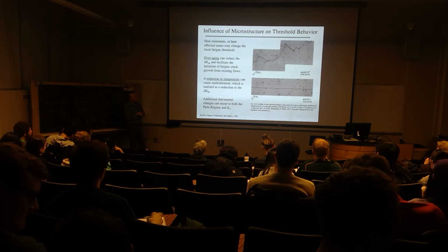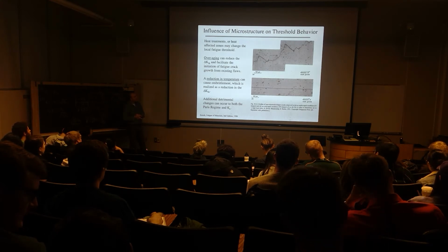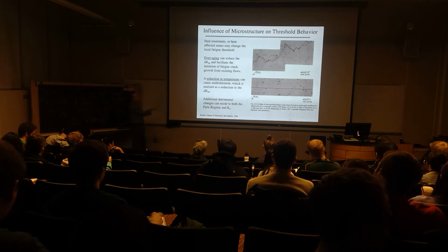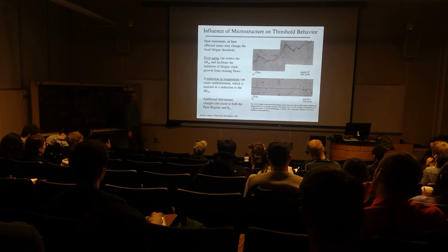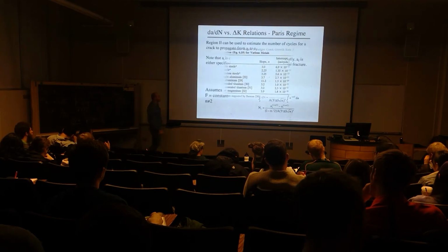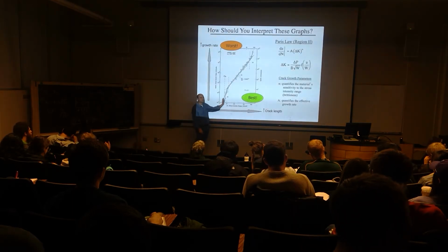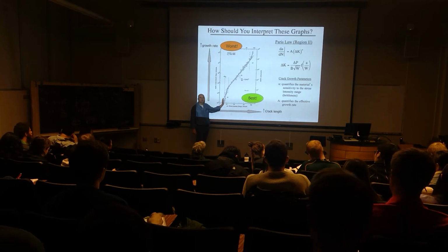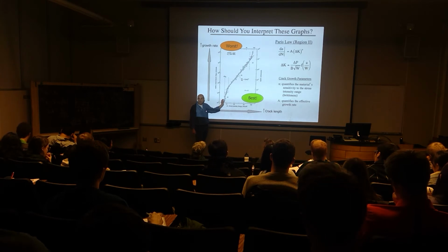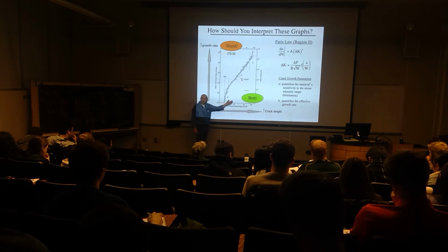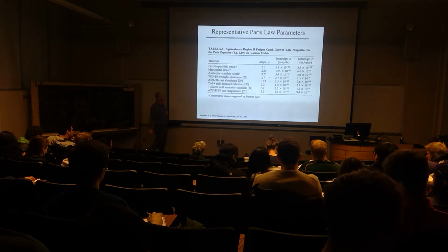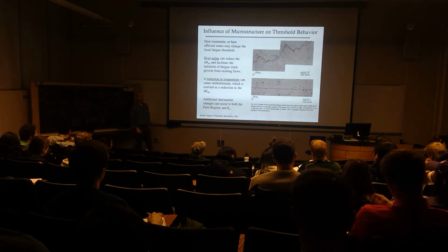Okay, so what can happen in our structures? One of the things that can happen is that we could have changes in conditions of materials that result from environment. So we could have heat treatments or heat affected zones which might change the local fatigue threshold of the material. I remind you that what we see in these fatigue crack growth diagrams is this stress intensity threshold. It's very specific to the material and its microstructure, because it's all based on the obstacles preventing that crack from being able to grow. Anything that changes those obstacles, their size, their effectiveness, can take away that stress intensity threshold.